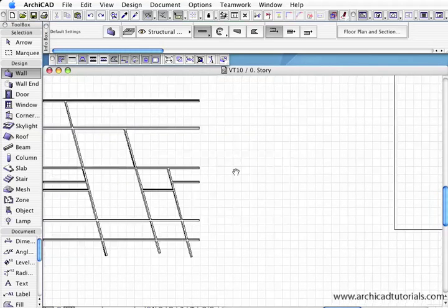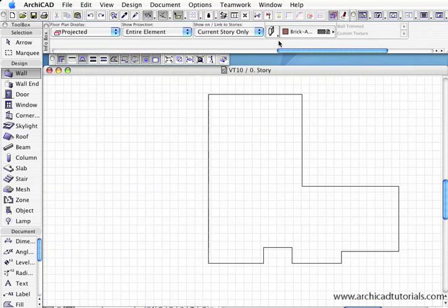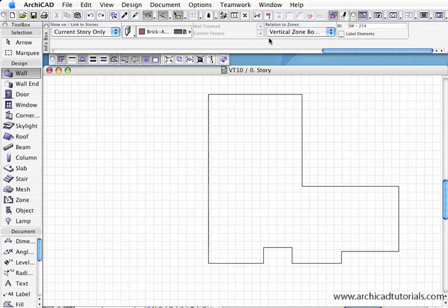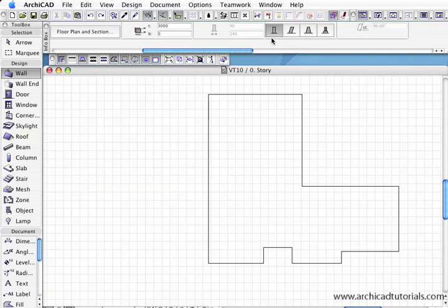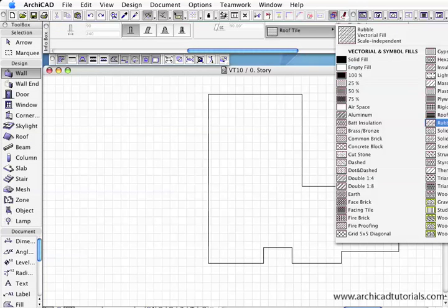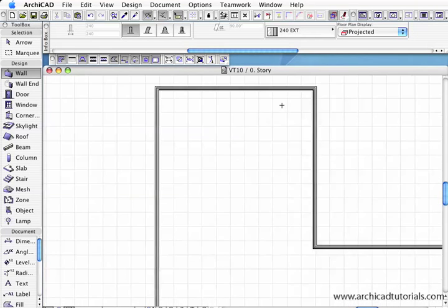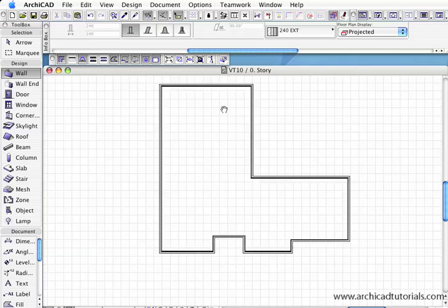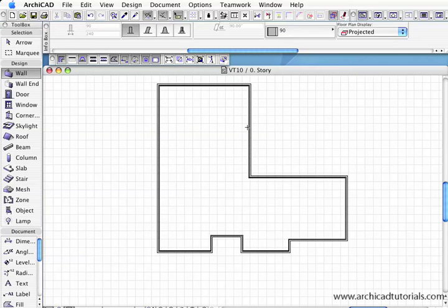So in a building type situation where we've perhaps already defined the slab, I just make sure I've got the right sort of wall first, and I'm just using the wheel to roll through those parameters. I'm going to hold the spacebar down and click, and around goes my 240 wall. Now I'm going to change the wall type to a 90mm plaster.